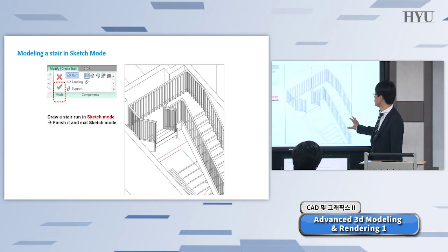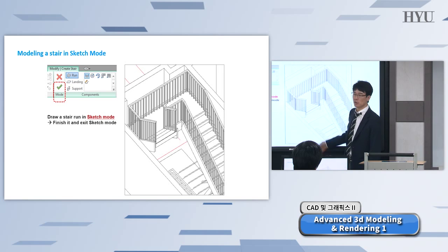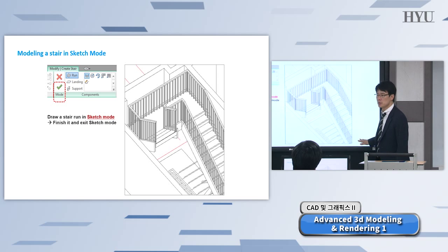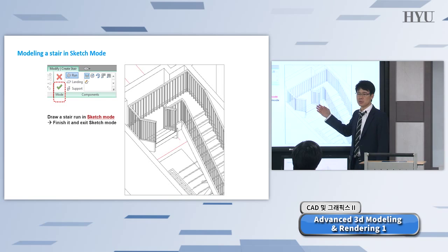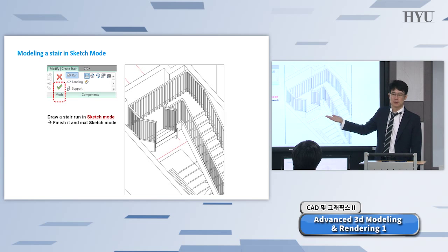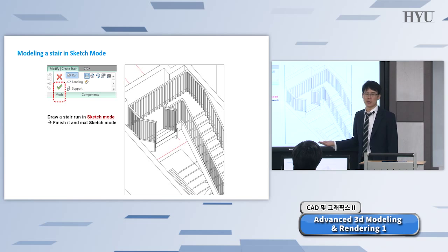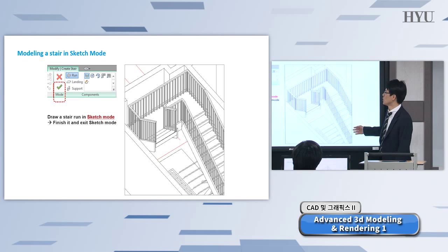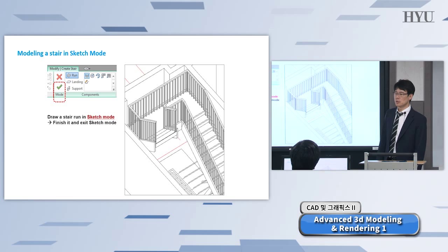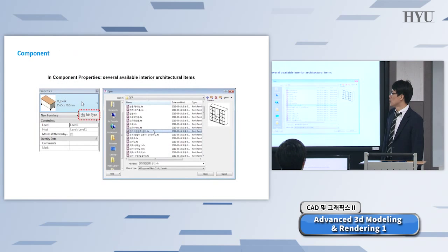So when you are working with this kind of stairwell object, Revit knows the bottom slab should touch the end edge of this stairwell, and the top end of this stairwell should be touching the upper level slab, okay? That's a kind of parametric definition and constraint. So that's why I'm saying this is an even more advanced and smart way of modeling.